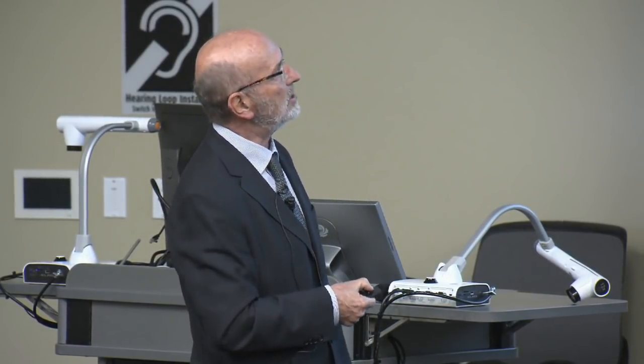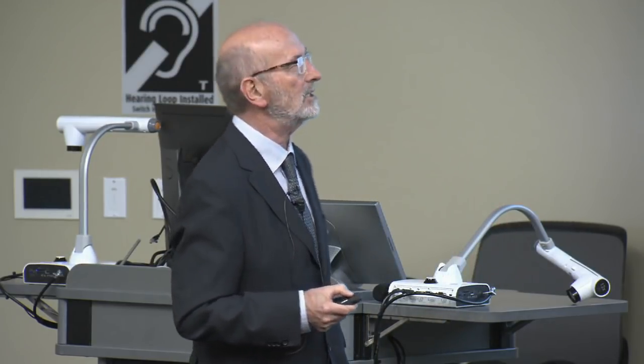And then here the compensation grouting starts. Just the starting of the compensation grouting creates, again, some displacement, but eventually they manage to compensate that and then get some constant value. And when they accepted that, the building didn't experience much damage, and it's successful to a certain extent.